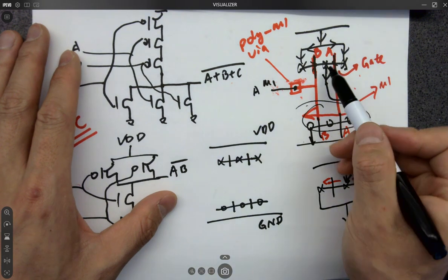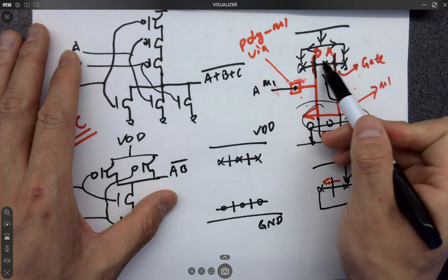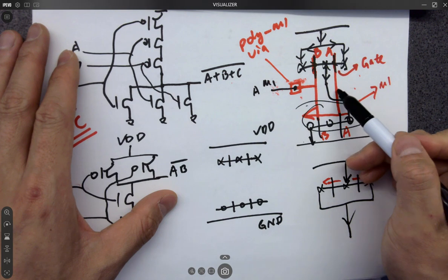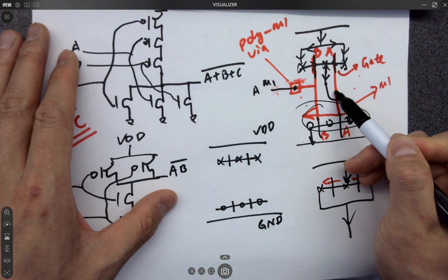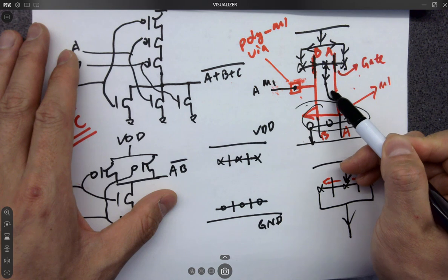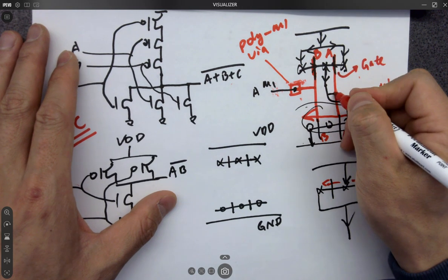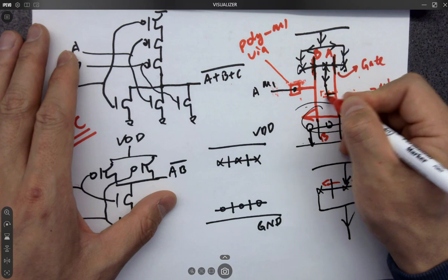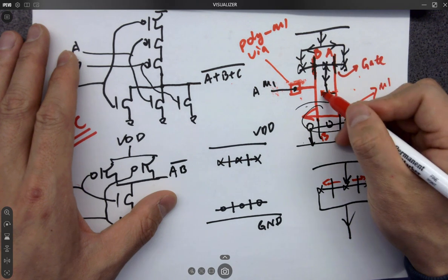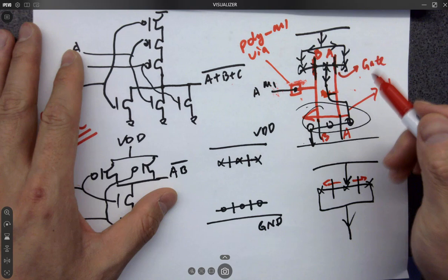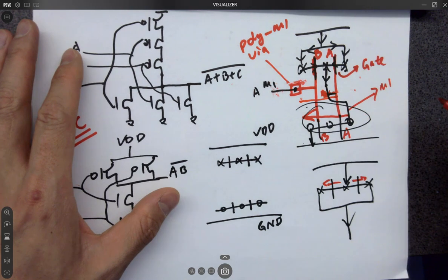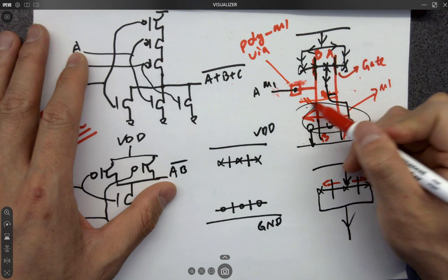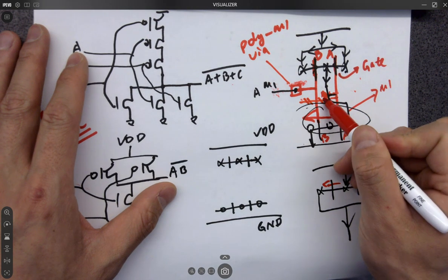You're complaining because the channel is too small, too short, and there's not enough space because the design rules have to be 1.5 lambda. So there's no space that allows me to extend this wire and make a little via here. No space. So what else can I do? Get the poly, and extend to here. No, it's getting shorted. It's shorting to this gate.